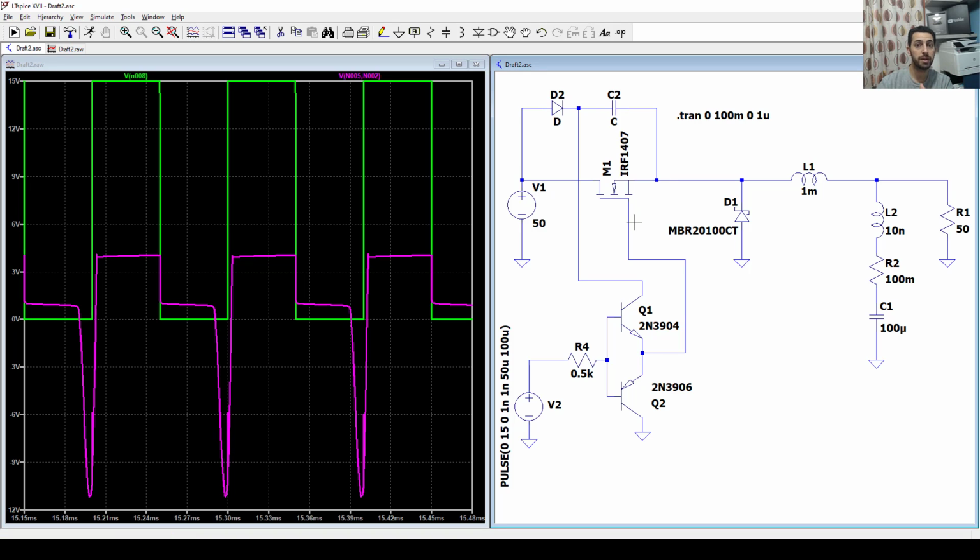So we have to make some protections, but I don't have any problem here driving that gate by this voltage, so I will keep it. Practically, you have to insert some protection diode or Zeners between the gate and the source, so any higher voltage will be clipped.